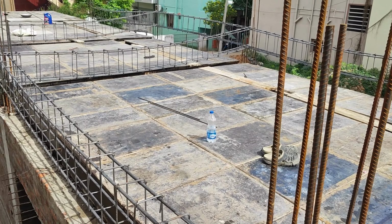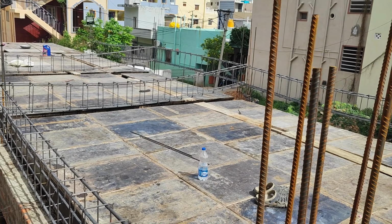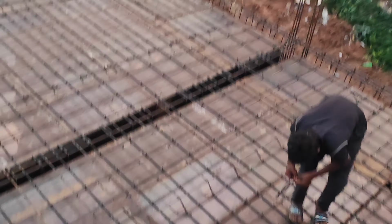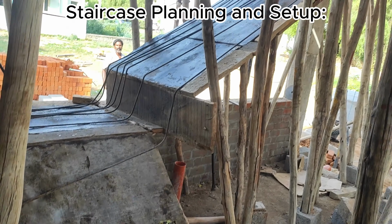Workers carefully place the steel shuttering and secure it with vertical and horizontal props to ensure there is no sagging or movement. Only after the centering is fully checked for alignment and load capacity do we proceed with the slab concreting.